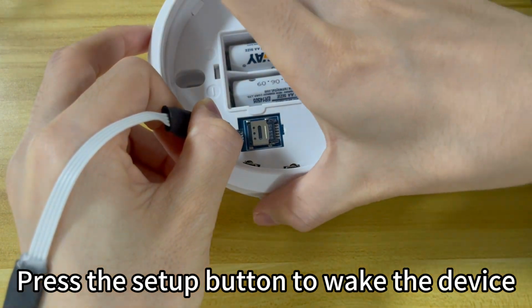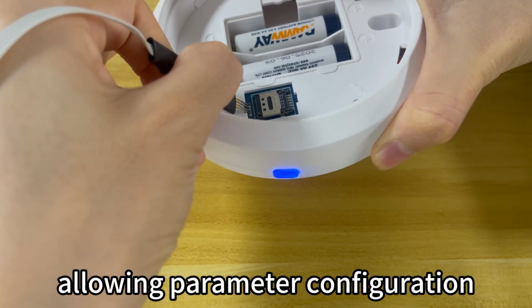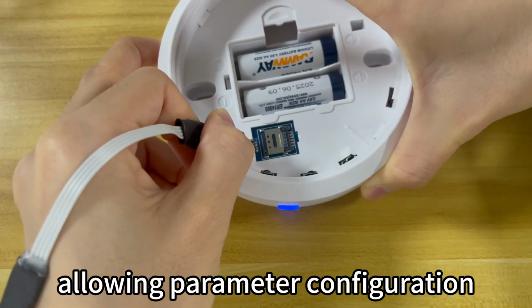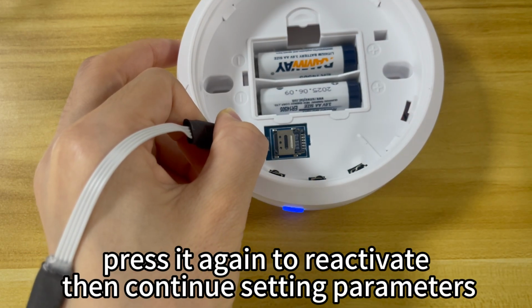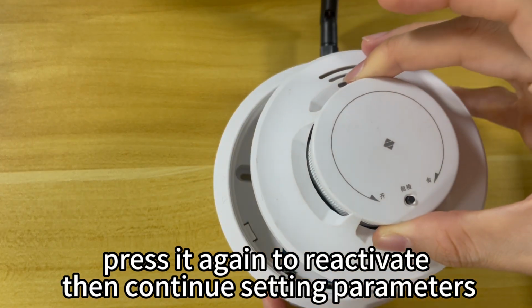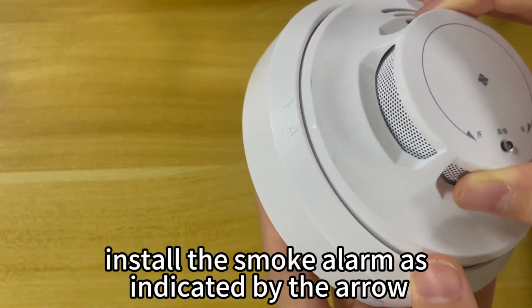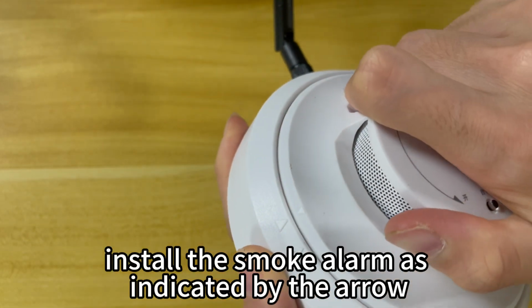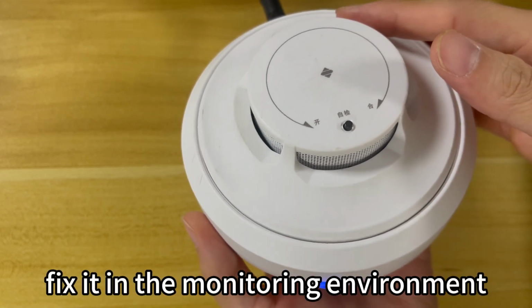Press the setup button to wake the device. The LED will enter a blinking state, allowing parameter configuration. If the indicator light turns off during setup, press it again to reactivate. Then continue setting parameters. After parameter configuration, install the smoke alarm as indicated by the arrow. Once installed, fix it in the monitoring environment.